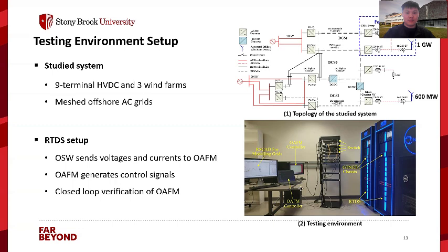The test system is developed and compiled in RSCAD and simulated in real time with 2 RTDS racks. The OEFM controllers are implemented and executed on personal computers in real time. RTDS sends voltages and currents to the OEFM controller. The controller runs the OEFM algorithm in real time and sends references back to RTDS once a fault is created. We conducted multiple cases, including balanced and unbalanced faults, to verify OEFM.